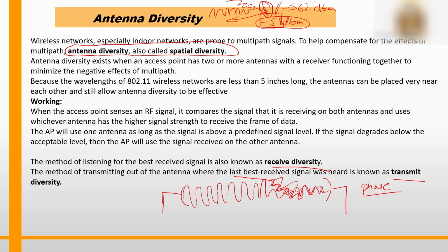With receiver diversity, the effects of multipathing are used for our benefit. If you have a single antenna, only one signal can be received at a time. Since you have two antennas spaced at a distance, say d, because of this spatial diversity, antenna A might receive the better signal and antenna B a slightly lower strength signal.